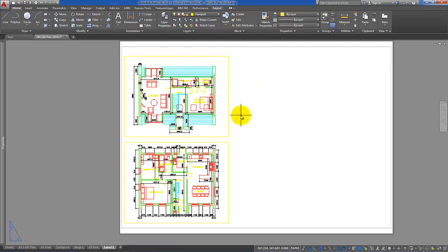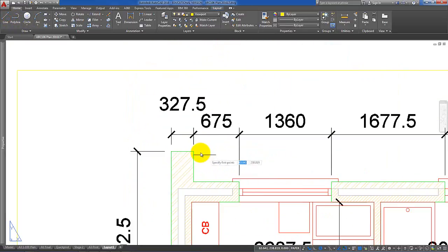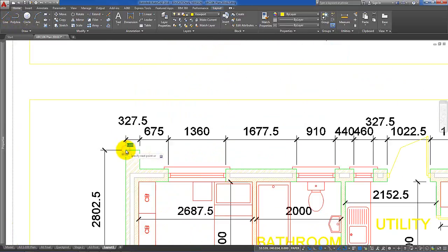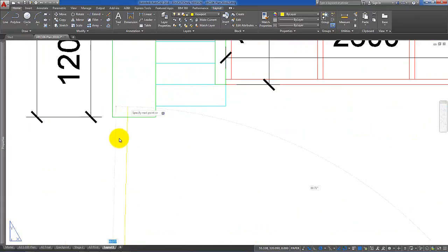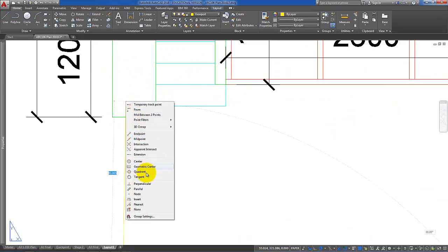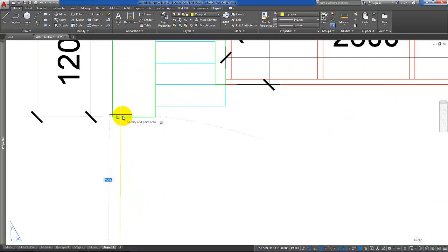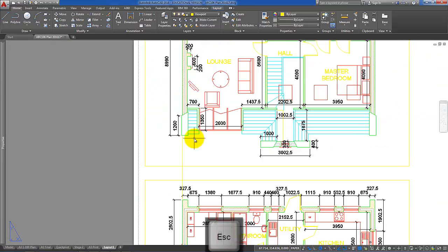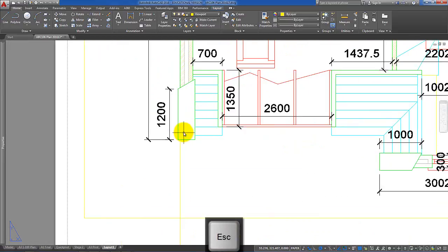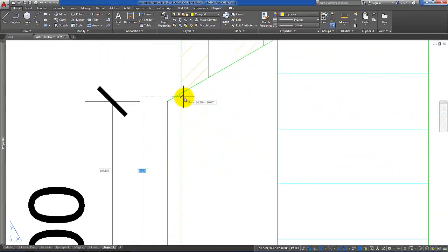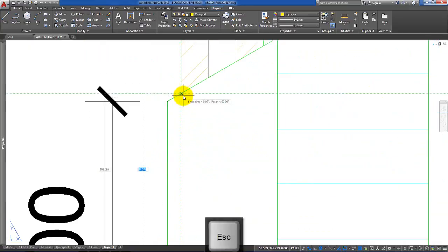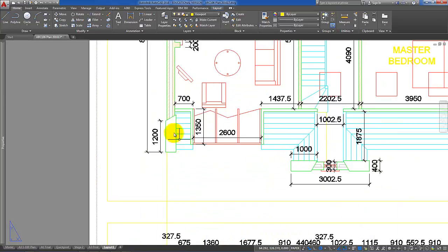We can double click out here in the viewport, and just to show you that these do line up, hopefully. Draw a straight line. We'll choose perpendicular. Now in this particular case, actually that is a capping stone there, so that will not line up, but it does line up with the wall at the next stage there, so we can delete that in the meanwhile.